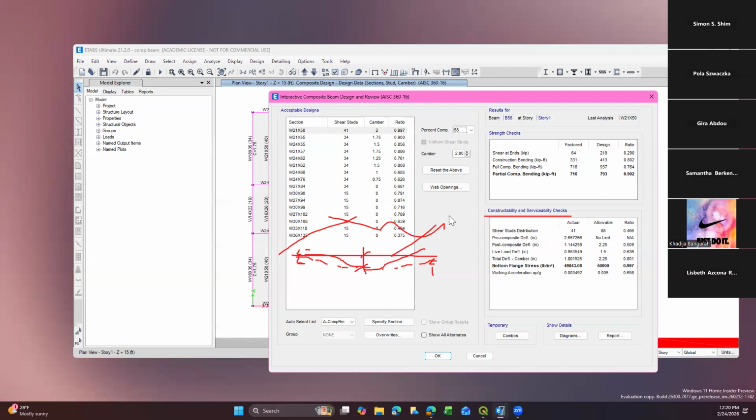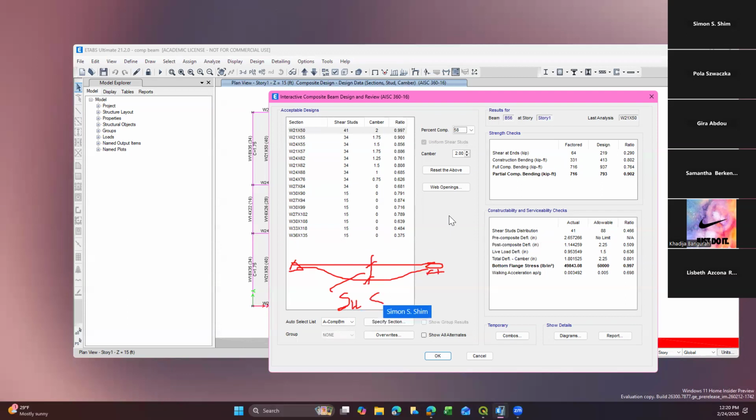So the building code has multiple serviceability checks and guidelines. First of all, easily remember that the vertical deflection delta under the live load we limit to span length divided by 360, right? So this is live deflection at the maximum span, L over 360.